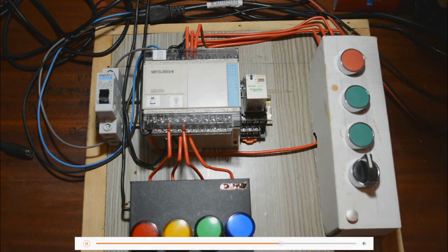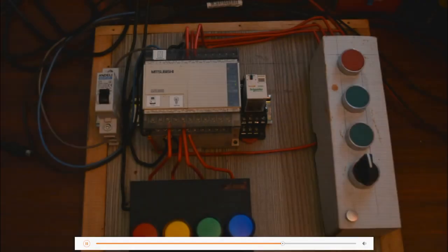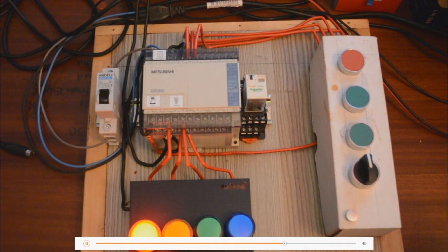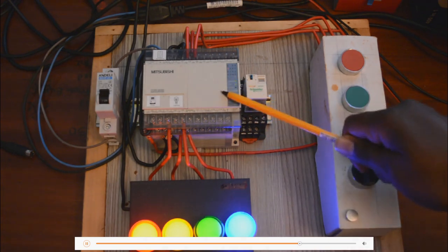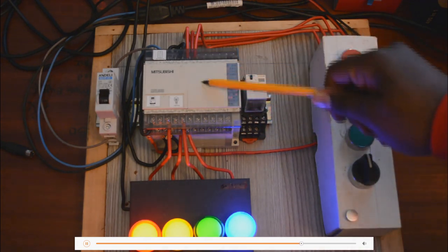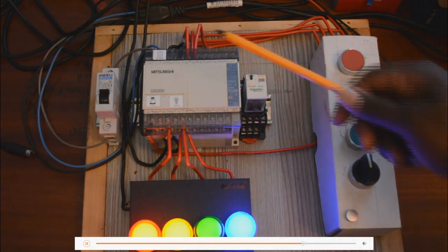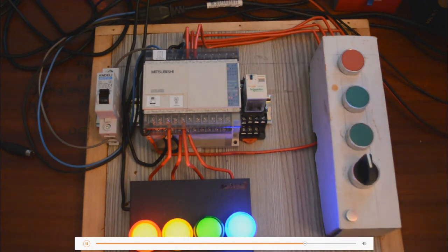So to show you how it works, let me press this reset button. Let me dim the lights so that you can see clearly. See, the red lamp has come on. Next you're going to have orange or amber, and then the program just runs on. It turns on the green lamp, and then finally the blue lamp will turn on. All these have been programmed at a set time. That's how the PLC works. Define time intervals between all your steps or all your outputs, so you have a program that runs over and over again.